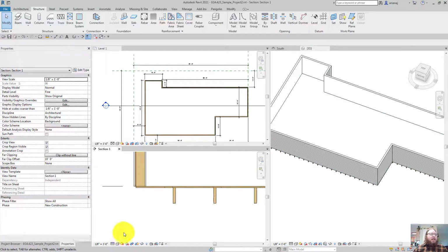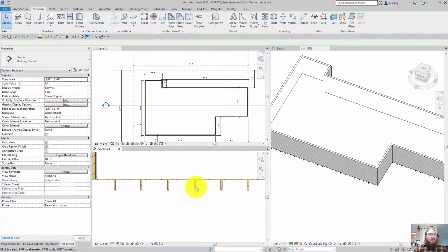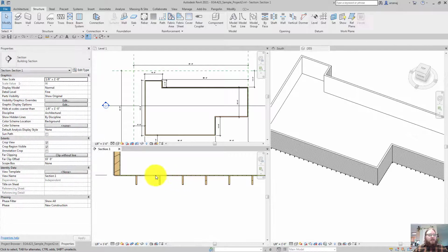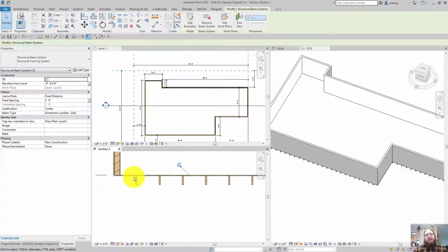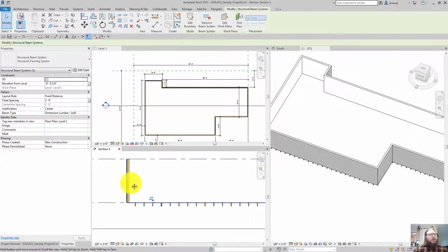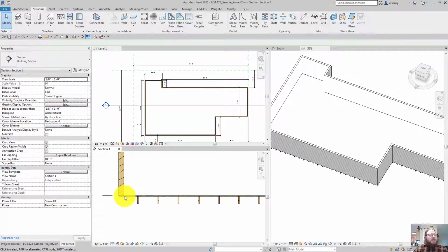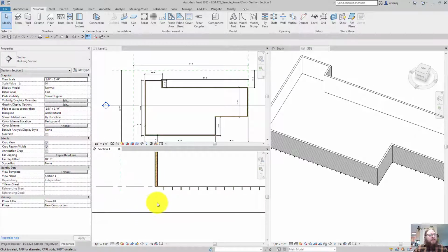Now I've quickly and easily just gone in and deleted the joist layer that was representing all these joists, because now I have all of these actual joists in here using that beam family. So I think we'll call that lesson good for now, and we'll go in here and figure out how to start putting in this stem wall next.